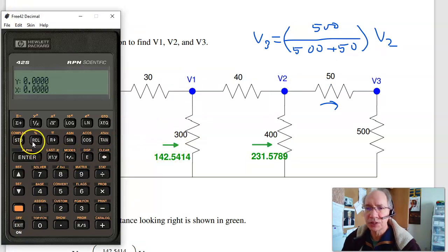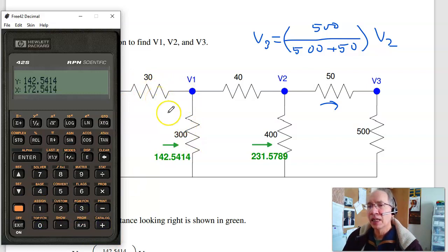Okay, so let's take this resistance, 142, that's why I saved it. Voltage division, and here I'm going to do a trick. I'm going to do enter, enter. That creates 2 copies of 142. Now add 30 to it. That's my denominator, R1 plus R2. And I hit enter twice because that made 2 copies, and lo and behold, there's the numerator. Take the numerator divided by denominator times 10 volts. This is 8.26 volts.